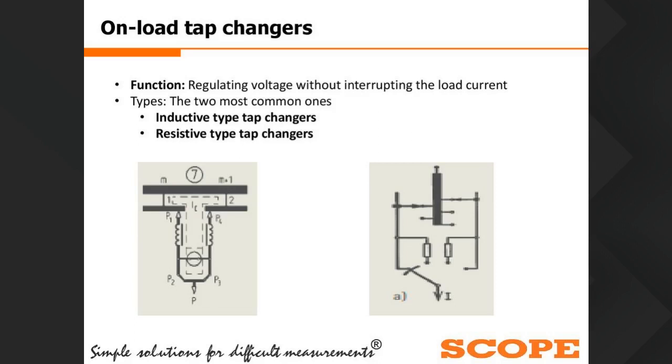About 30% of failures in a transformer are due to OLTC issues. So this is a very important test, and it is important to monitor the healthiness of the OLTC. Basically, as everyone knows, the OLTC or tap changer is on the HV side of the transformer.